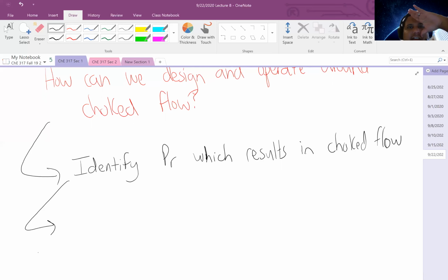Because of the rocket nozzle design, you're not going to be able to manipulate the throat, and you're really not going to want to. The diverging section maybe a little bit, but the more flexibility you're going to have is in that converging area for the reservoir pressure.